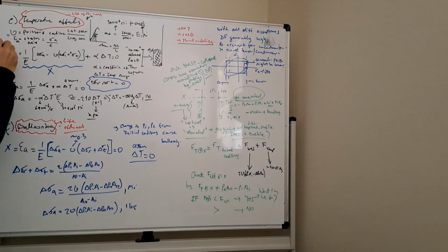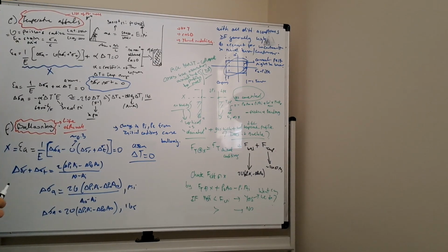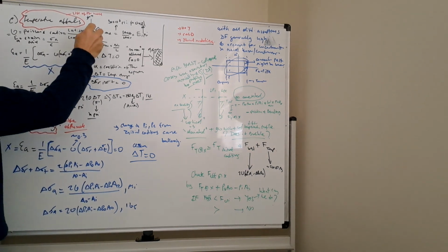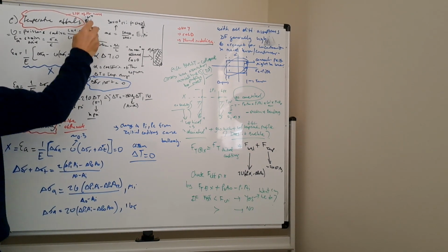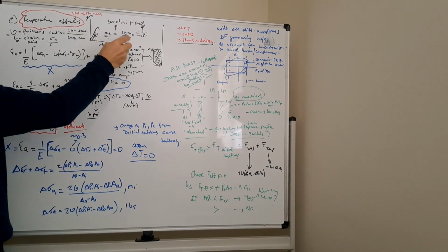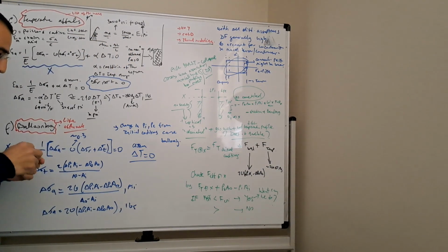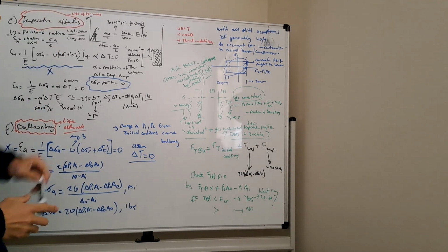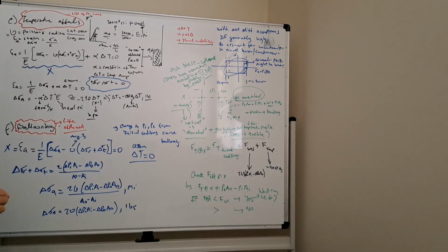And then here I also define a strain. What was the strain? If you remember this plot from part number 1, that was the elastic region, stress and strain, and tangent alpha, that was the slope, that was equal to the Young's modulus, which is around 30 times 10 to the 6 psi for steel.